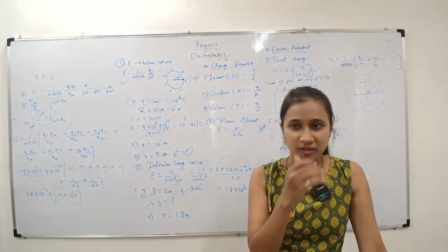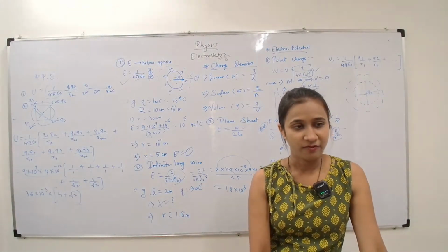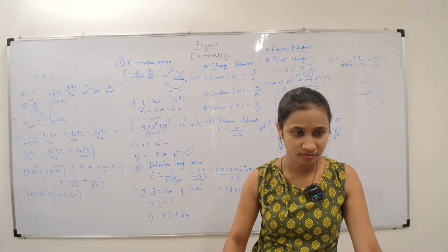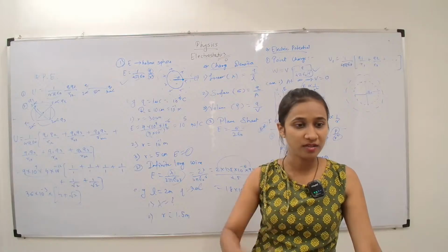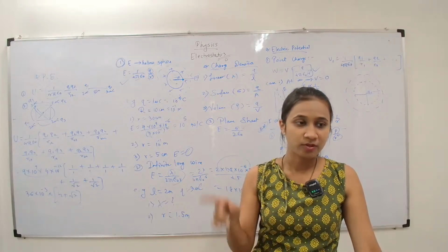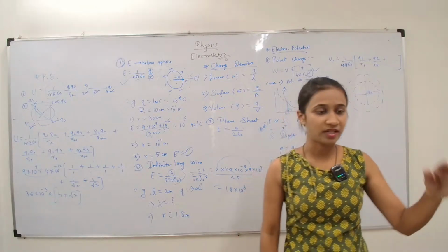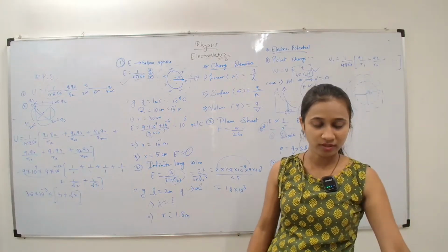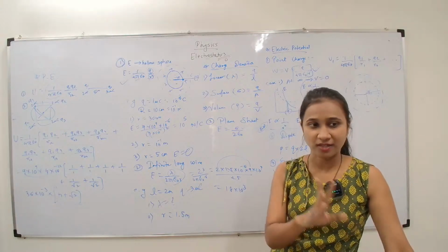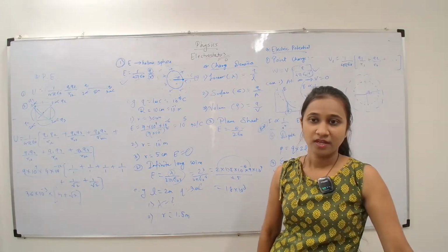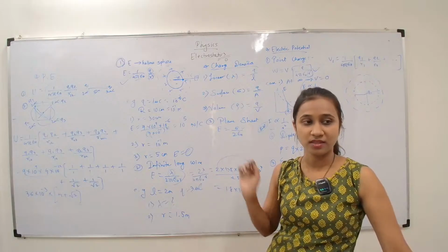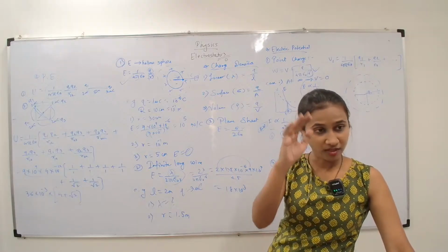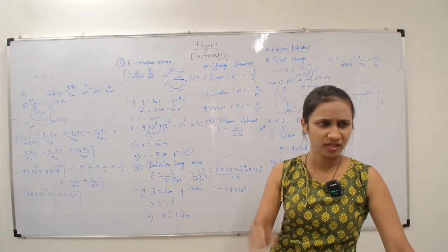So, do you know about resistance, current, electricity? If I arrange the resistors in series, the total resistance is simply the addition. If I arrange them in parallel, it is the reciprocal of the sum of reciprocals: you take reciprocals individually, add them, and at the end find the reciprocal again. In exactly the opposite manner it is for capacitors. If capacitors are in series, the total capacitance is the reciprocal of the sum of reciprocals. If they are in parallel, the total capacitance is simply the addition.